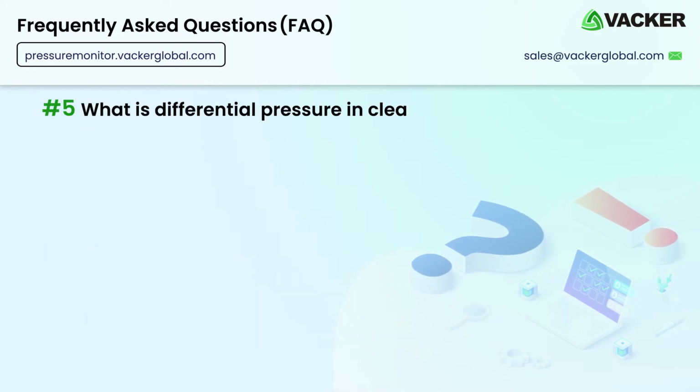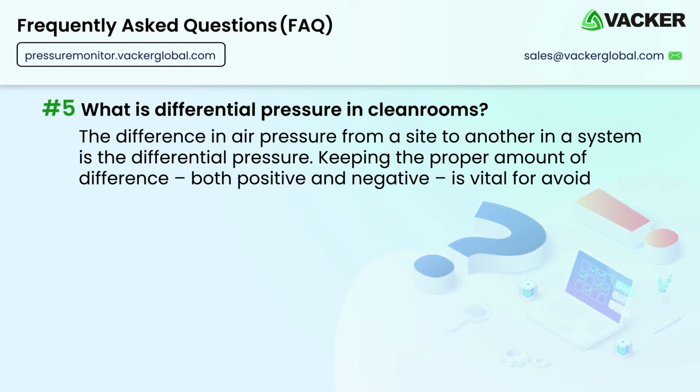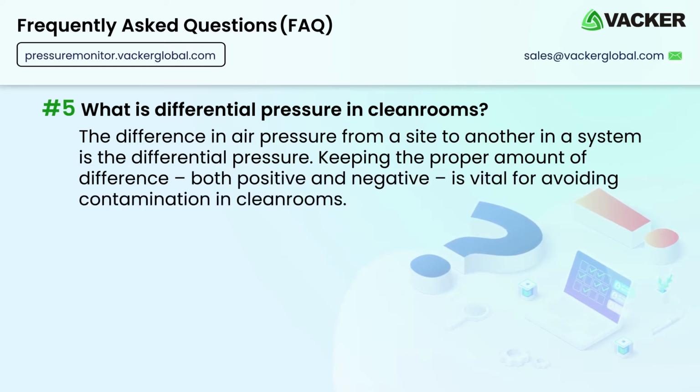What is differential pressure in clean rooms? The difference in air pressure from one site to another in a system is the differential pressure. Keeping the proper amount of difference, both positive and negative, is vital for avoiding contamination in clean rooms.